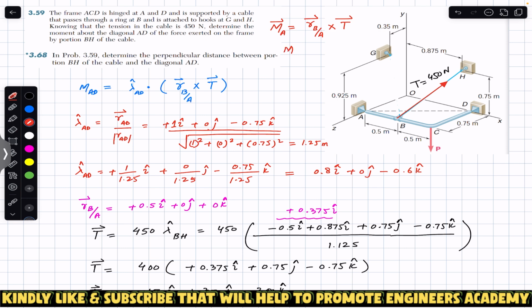Or we can find the moment about point D, and that will be R of B relative to D cross product with that tension T. So this will give us the vector representation of the moment about point A or D. And then, if you want to find the magnitude of the moment about AD, we will take the dot product of one of these with the unit vector from A to D.